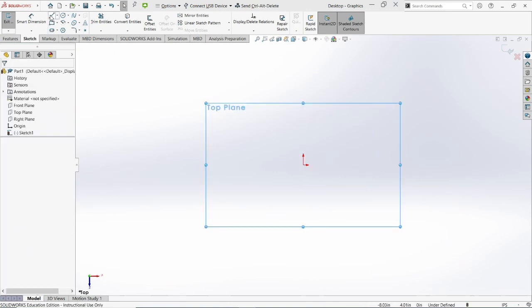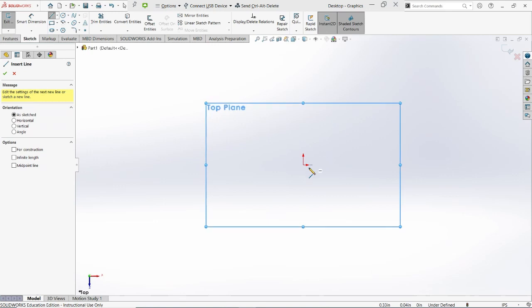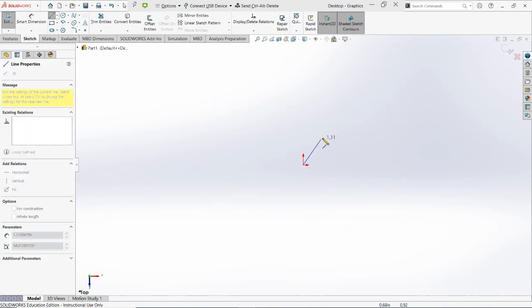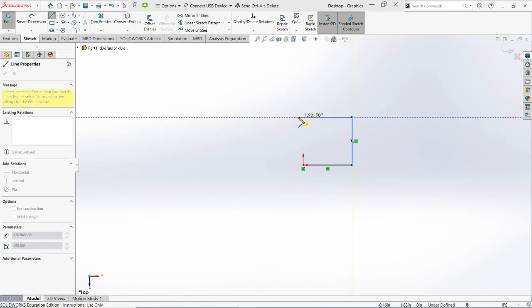I'm going to do that again a little bit slower. I'm going to wait over here, click on the origin. You can see that it snaps that point on. So I go over, see that little orange dot, click once to place one endpoint, click again to place the second. It has already created another endpoint for me, so to create another line, I'll just click one more time. Now I have two. Repeat that process for the next two lines.